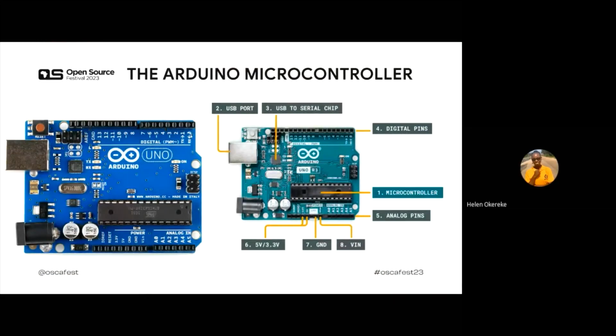I talked about the TX and RX. So the TX is transmission and RX is receiving. So when you want to work with maybe a Wi-Fi module or Bluetooth module, for the projects where you can talk to your phone, and then your phone will send a signal to the Arduino, these are exactly the pins that you need to connect to. You need to connect your Bluetooth or your Wi-Fi to the receiving pin. That is the work of these 0 and 1 pins.